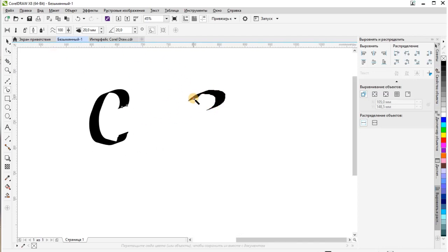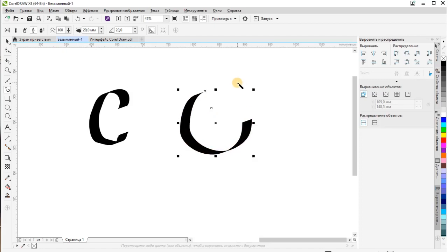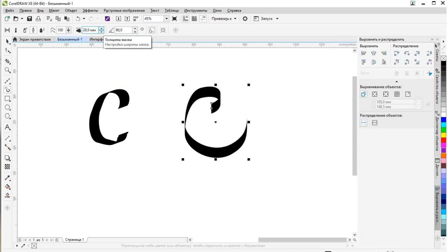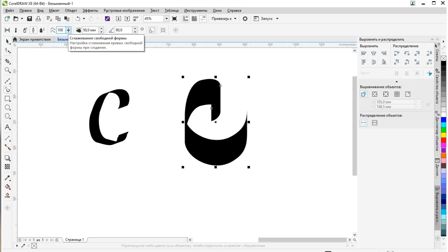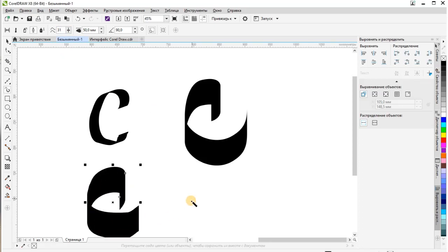However, after the end of dragging, after releasing the mouse button, another object is automatically drawn, a closed curve. Its shape is determined by the shape of the control line and the characteristics of the calligraphic pen: the width, set by the line width counter, and the slope, set by the value of the calligraphic angle counter, which replaces the preset in calligraphy mode in the Attributes panel.